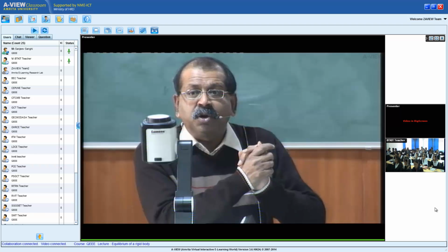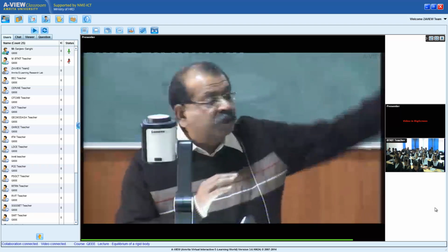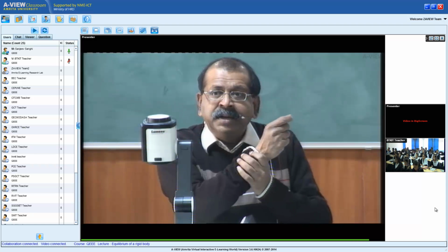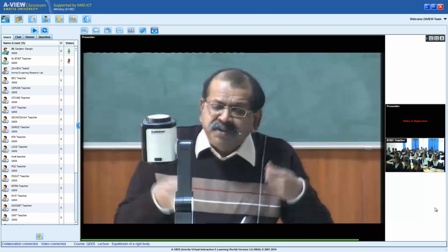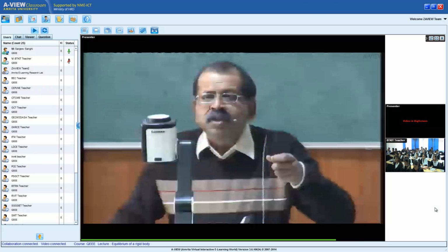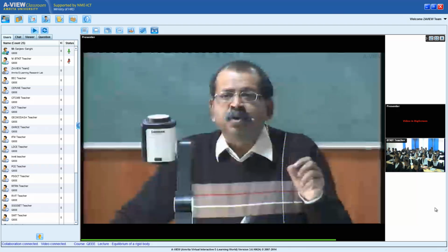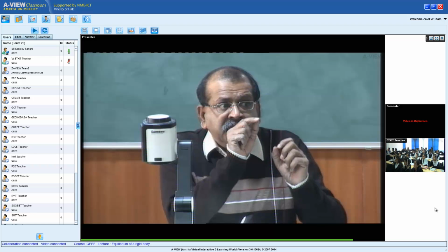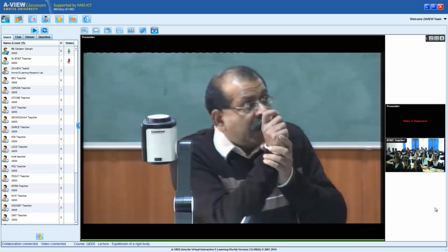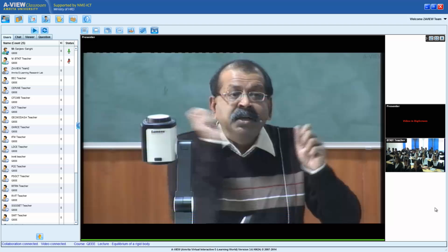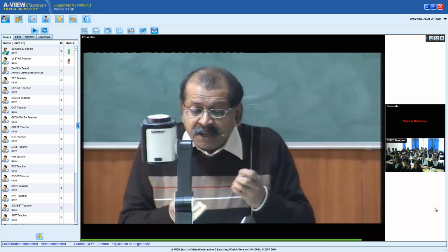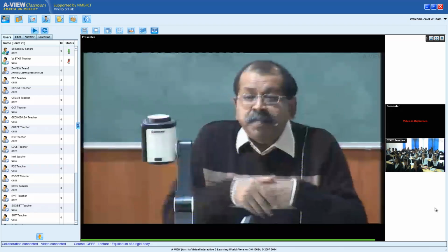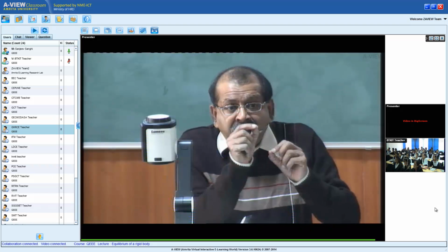Suppose you're hammering a nail on the wall and you're looking at the total wall, you want to see what force is applied on the wall, then we will treat this nail for our purposes as a discrete force. But if I'm interested in just studying the effect on the wall at the point where the nail is being hit, then treating this nail as a discrete point may not suffice. And I may have to look at the details.